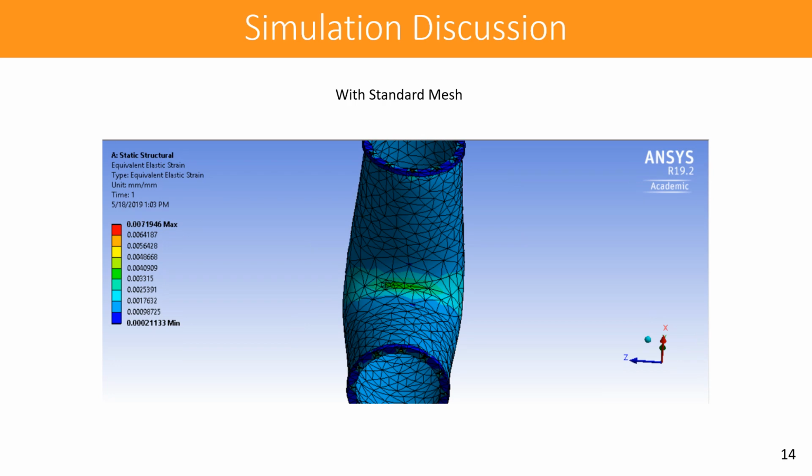So the strain profile is almost negligible. The only significant strain appears in the under part of the elbow, in the units of millimeter over millimeter, about 0.0040909. So it's not a whole lot of strain. It's very, very far from the rupture conditions of what P91 usually ruptures at.